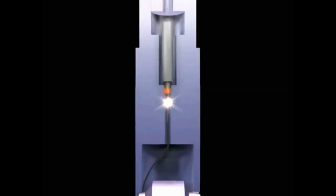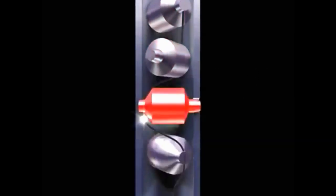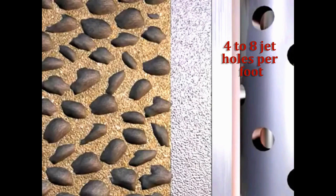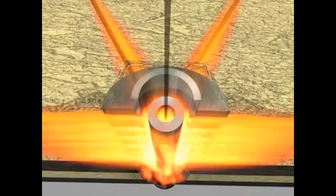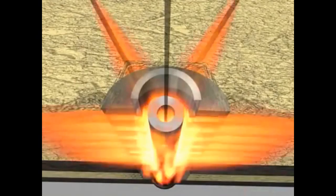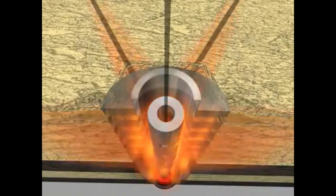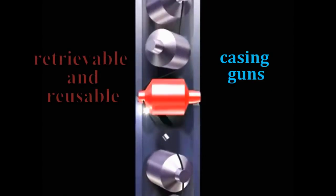To blast through the casing and cement, jet perforators are set to blast on average 4 to 8 jet holes per foot. Each shot is rotated 90 degrees or 180 degrees from the one above throughout the pay zone. To blast these jet perforators through the casing and out into the formation, casing guns are used. Both retrievable and reusable, these casing guns are made of strongly constructed steel which are run on an electric wireline.